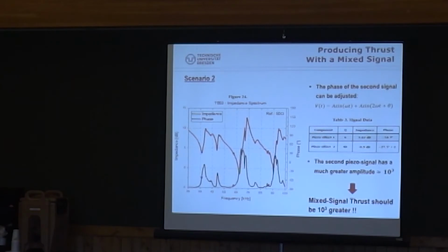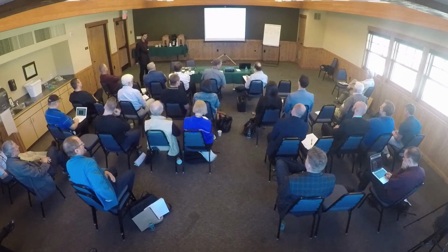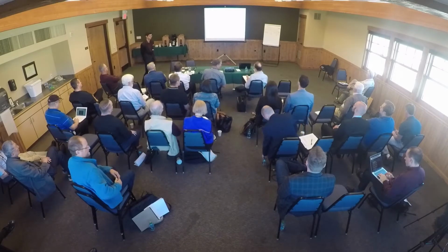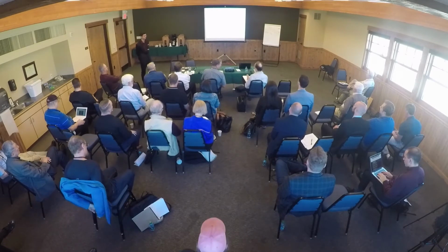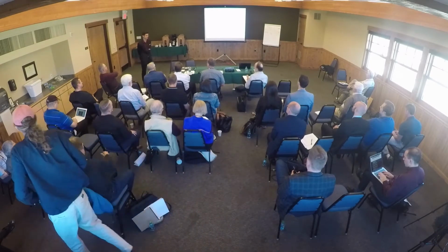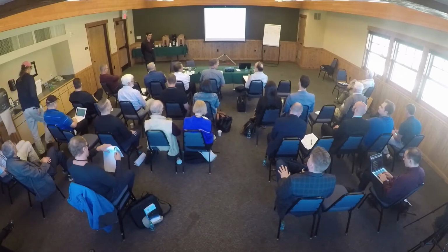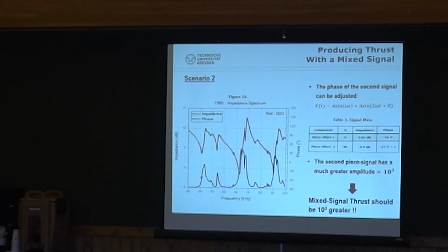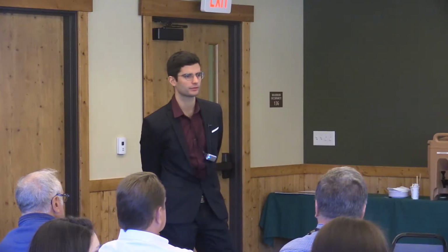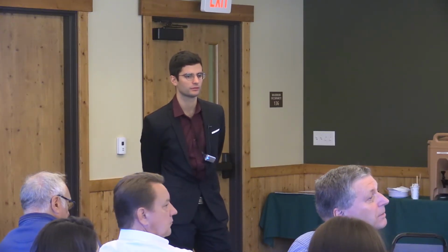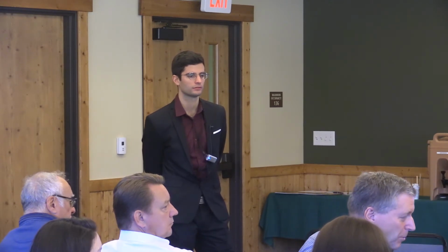Okay, this is another thing on terminology. For the electrostriction, the excitation frequency has to be at the subharmonic of the natural frequency, not as a superharmonic. That means, for example, if you're looking at the 2 omega t, then the excitation frequency has to be at half the natural frequency. Are we in agreement or not? No, I'm not in agreement. Okay, well. Not if you DC bias it. So yes, it does. Then the frequencies would be, no, the same.